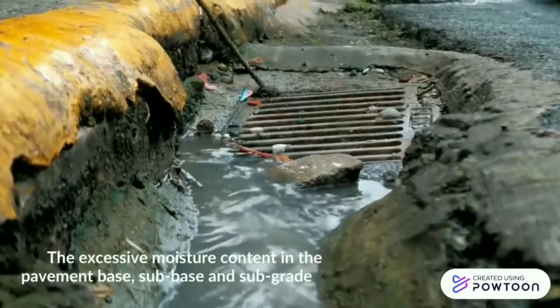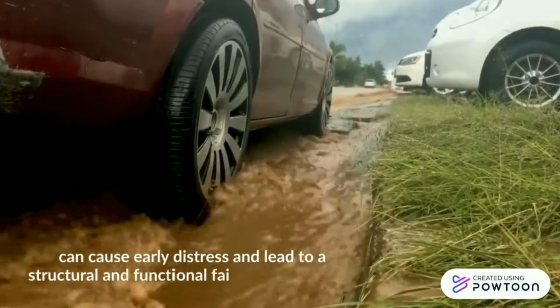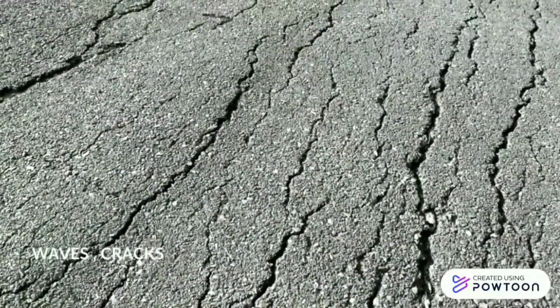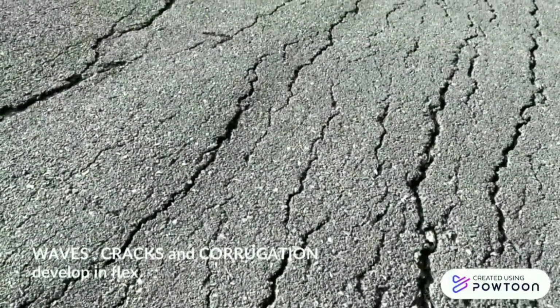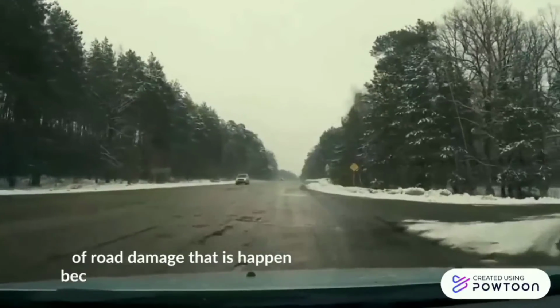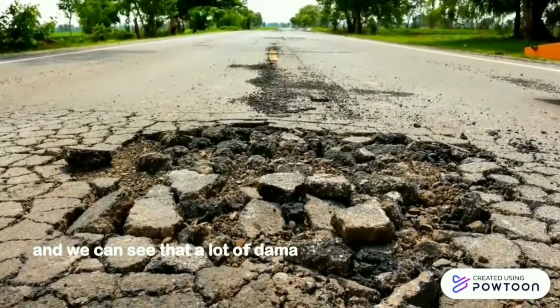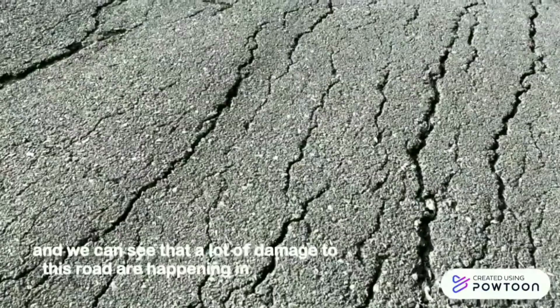The excessive water content in the pavement base, subbase, and subgrade soils can cause early distress and lead to a structural or functional failure of pavement. Waves, cracks, and corrugation developed in flexible pavements are an example of road damage that happens because of high moisture content. And we can see that a lot of damage to roads is happening in Malaysia.